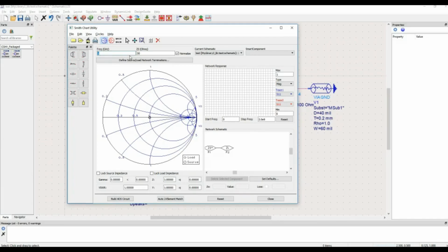so you can define the frequency. You can define your source impedance. For example, if it is an SMA port termination like this design, you can keep it 50, and then clicking normalize, it will normalize the loads by dividing every impedance by 50. So you can either have normalize or just leave the normalize here.